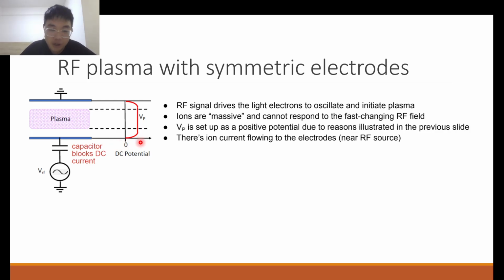we do etch, we want to accelerate your ions near the wafer so that they bombard the wafer. And how do we accelerate the ions at the wafer? We have to accelerate them through an electric field, an electric field that acts on these charged ions to accelerate them. Okay, so this is a very important phenomenon, and this is why it allows this kind of plasma etch to occur even with an RF bias.